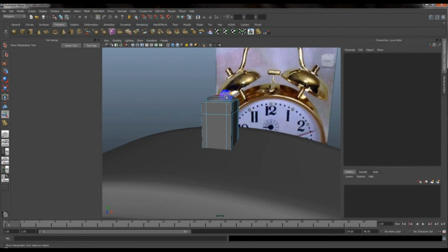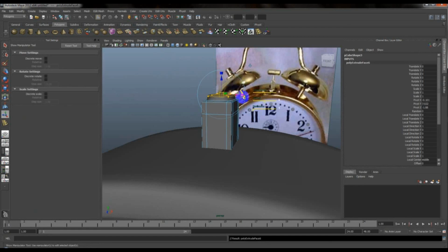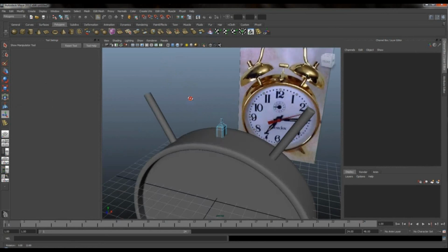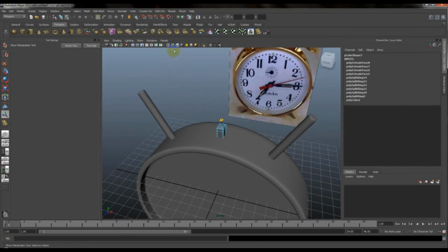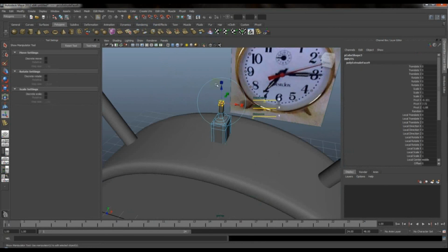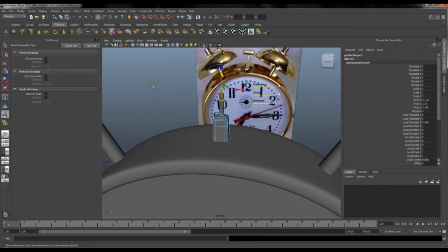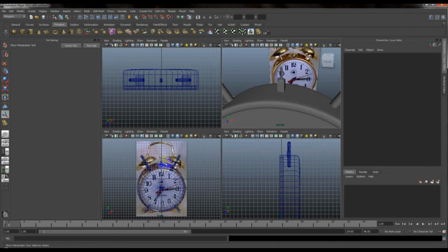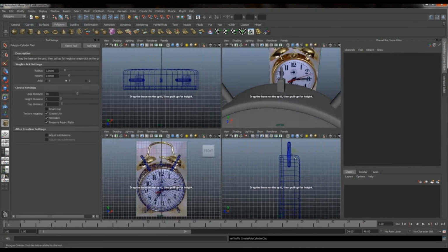Maybe that. I'll select the upper face again and extrude it again. No, sorry, scale it down first, and click G to extrude. Place its size, make another extrude, and yeah, that's somehow a good result. That looks much more similar to the thing that I want. Maybe extrude it much higher, and yeah, that's good. That's enough for me. I go to object mode of this object and go to the front view again and